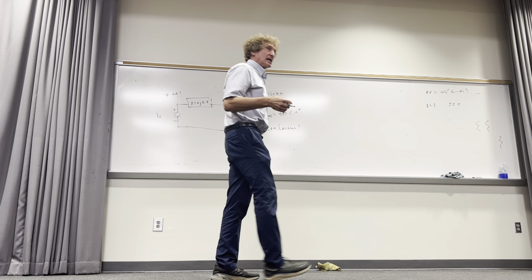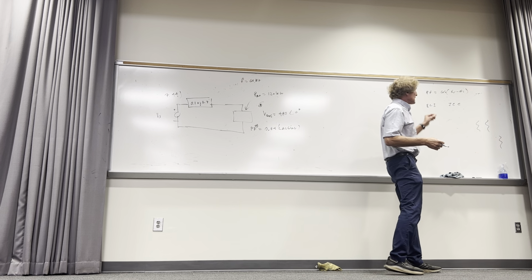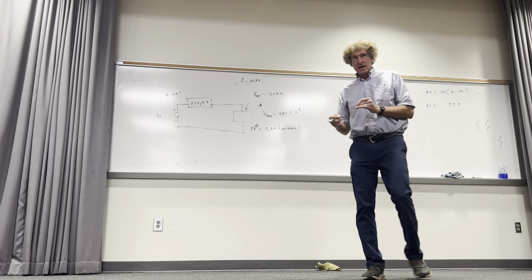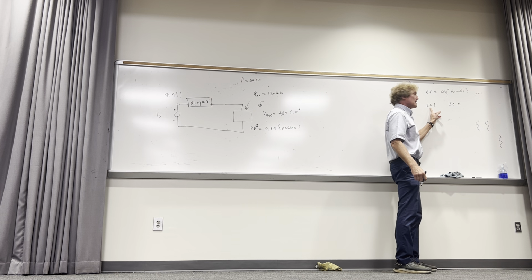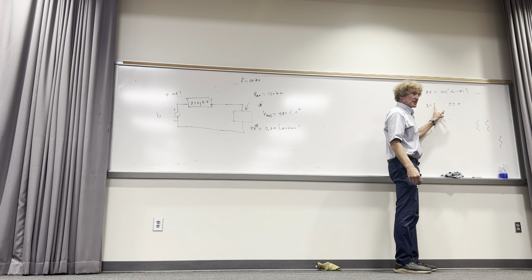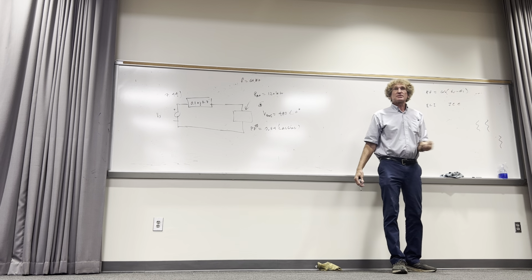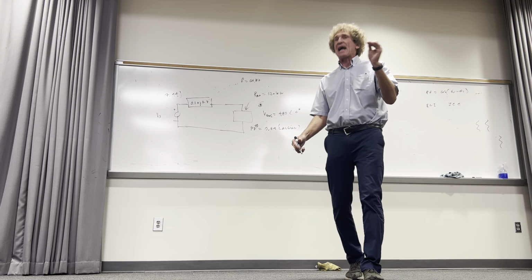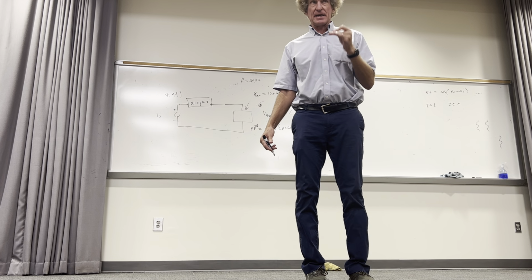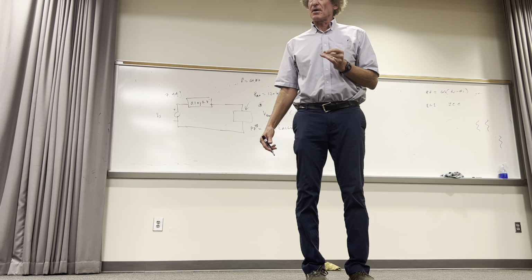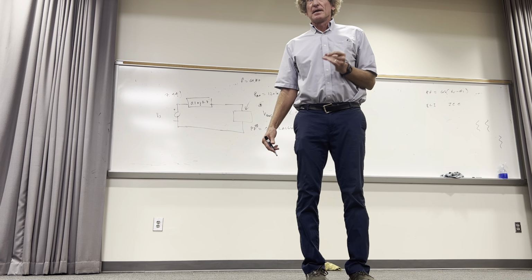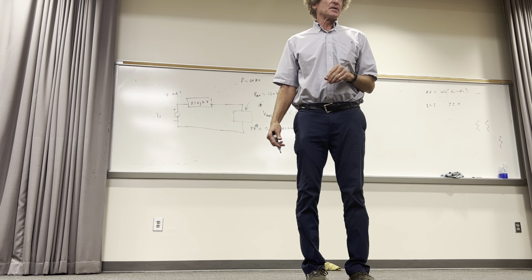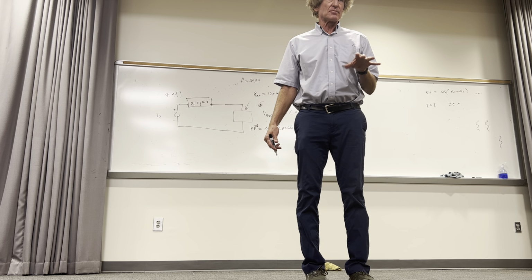Now, a difference is in England and in some areas, E is the symbol for voltage, and I is the symbol for current. So when they say ELI, here you see E, or voltage, is ahead of current. You all see this? When voltage is ahead of current, the current is lagging, or the power factor is lagging. If it's leading, which is extremely rare, then that means that the actual voltage has an angle that's ahead of the current angle. And some of this is going to have to be made clear with examples.